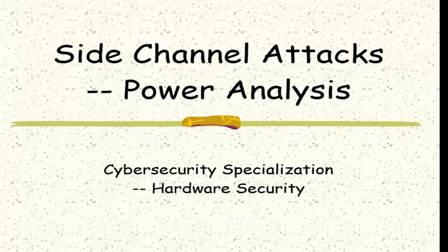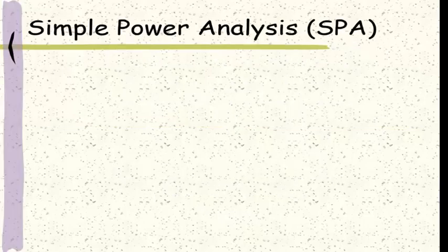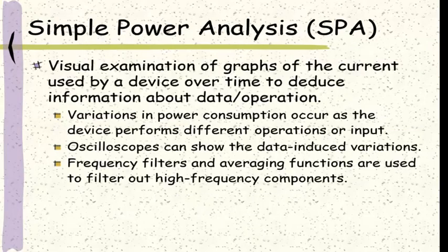We now discuss the power analysis attacks. We will cover both simple power analysis and differential power analysis. In simple power analysis, the attacker attempts to visually examine the system's current or power waveforms during execution in order to discover information about the data or operation.